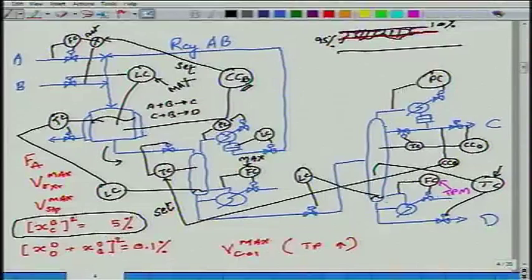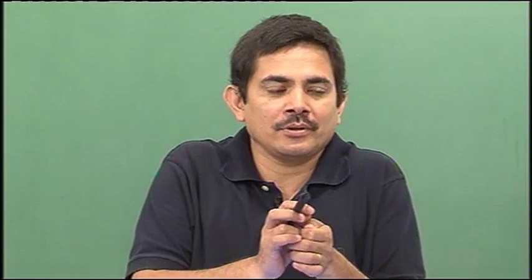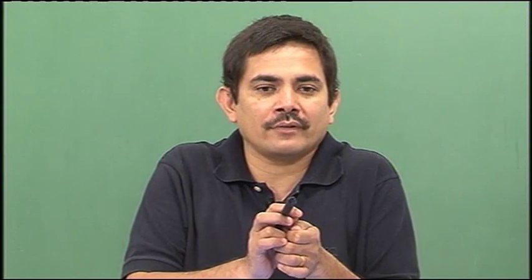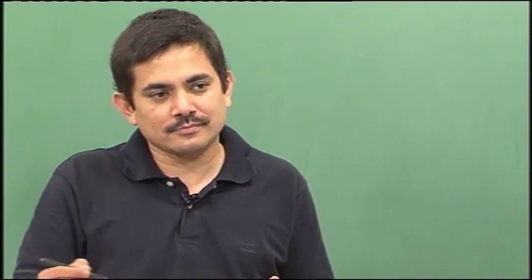CCB, this guy. If there is any mismatch in the fresh A and fresh B, composition controller will adjust the ratio, make minor correction to the ratio set point. Maybe it goes from 0.95 to 0.955 or 0.945 or whatever, so that any slight mismatch is properly accounted for. Does this make sense or no? Fine. So I start jacking up the throughput.